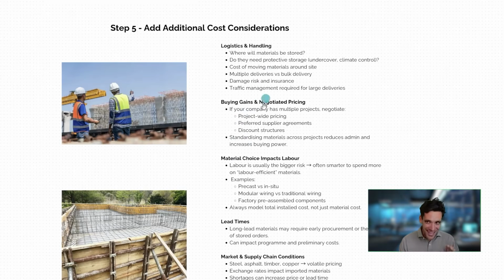So by logistics and handling, I mean, where are they getting delivered? Where are they getting stored? How are they getting transported from where you're storing them to where you're installing them? Do they need to be undercover? All these things have to be thought about.